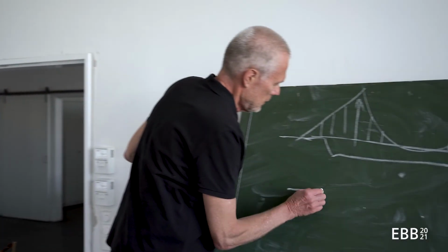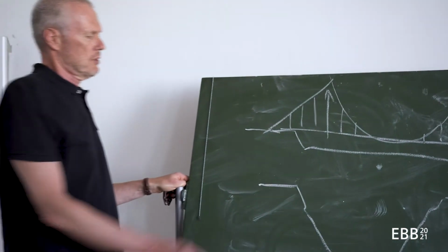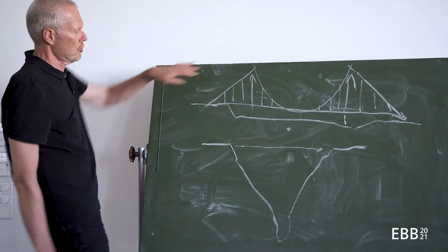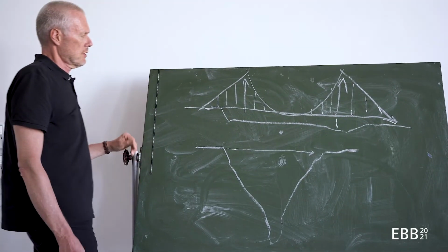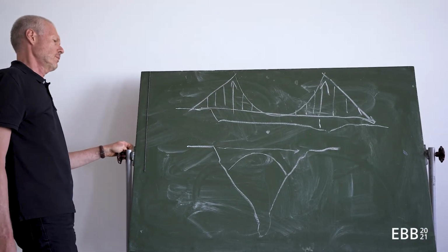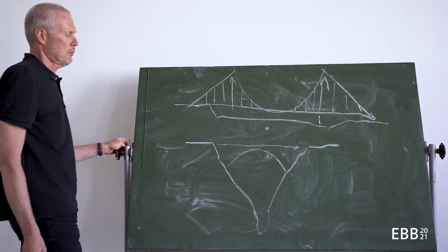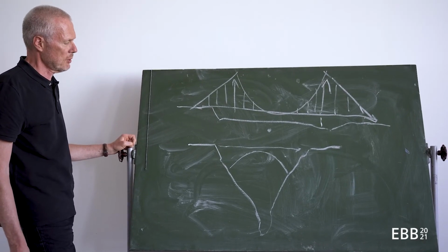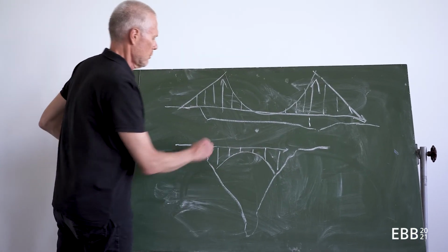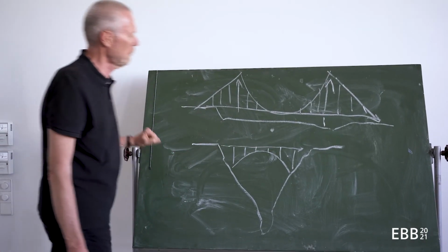If I have a different situation, like for example in the Alps, so I have a valley and I want to get from one side of the valley to the other, I could use an arch structure as well, which is a little bit the inverse of what we have seen before. So here I have a lot of space below, could place an arch. The ideal form would be the one that we have seen in our suspension experiment before. And then I could link this arch structure to the driveway and get some sort of horizontal load-bearing structure as well.